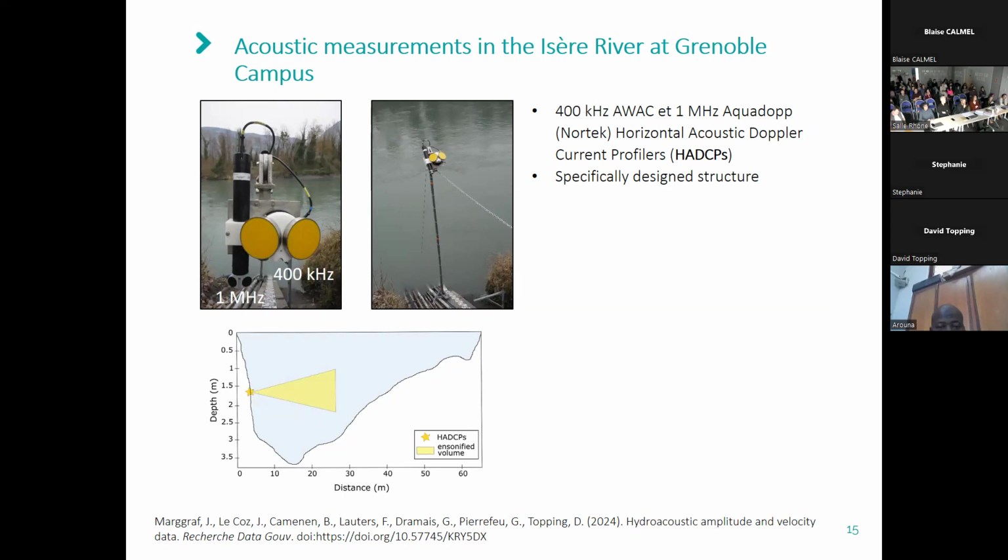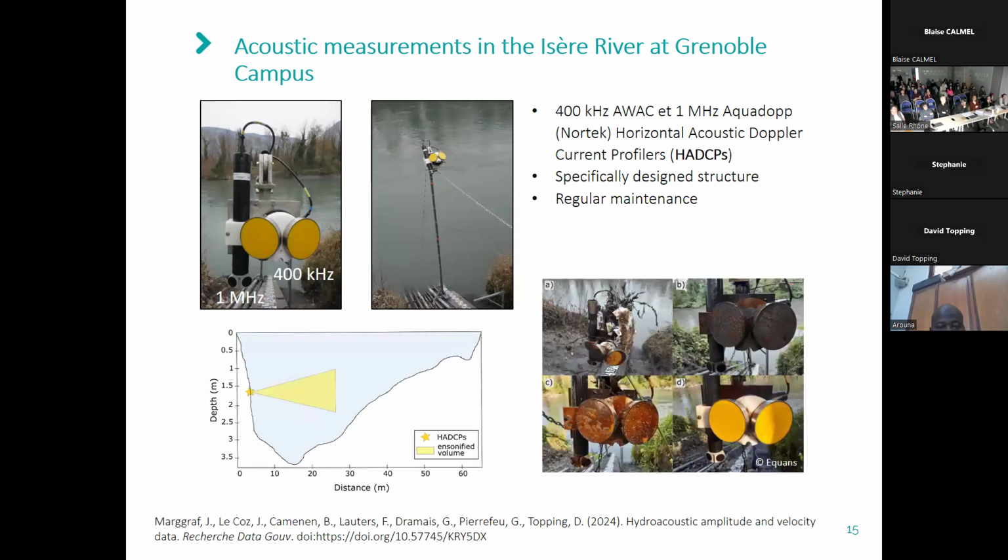At the same time, you can see here that we used a specifically designed structure that allows us to flip the instruments up and down and also to take them out of the water to perform maintenance. We perform regular maintenance with our partners, and I also verified that debris and biofouling have no influence on our acoustic measurements.